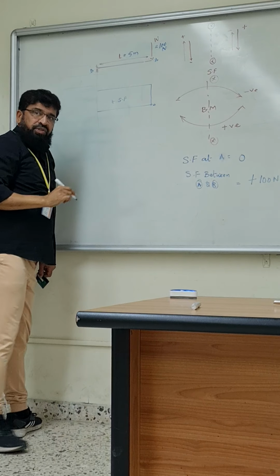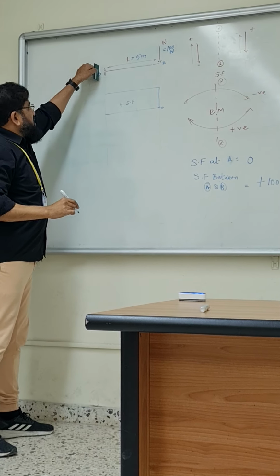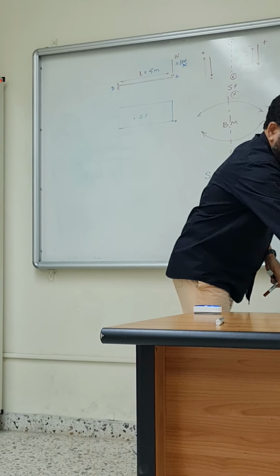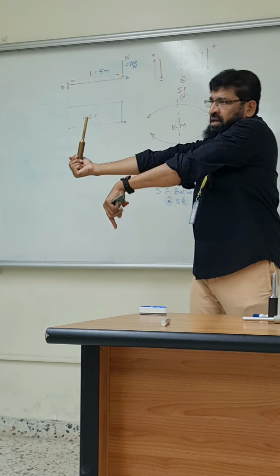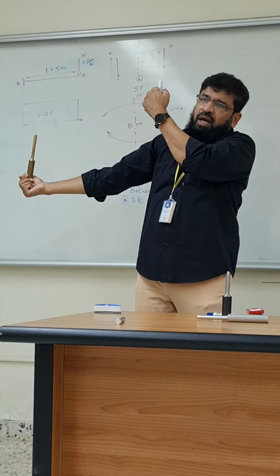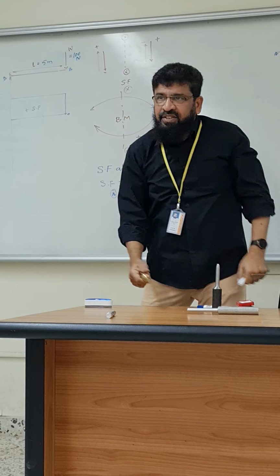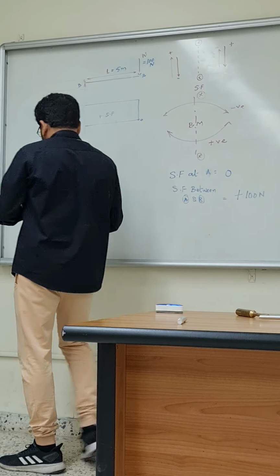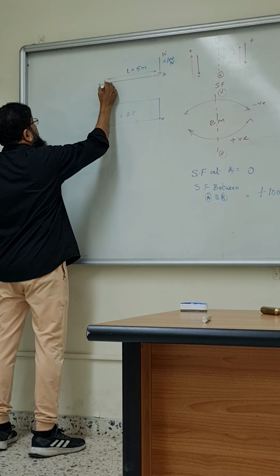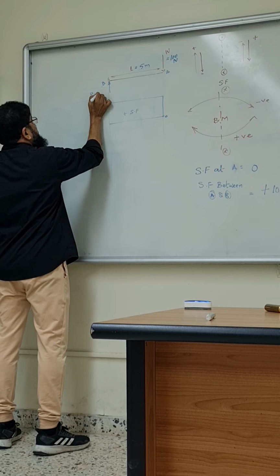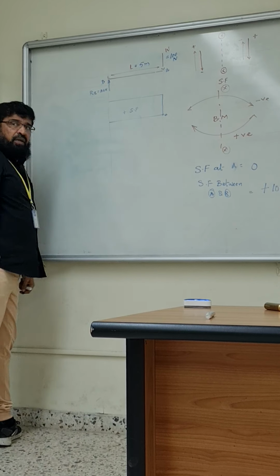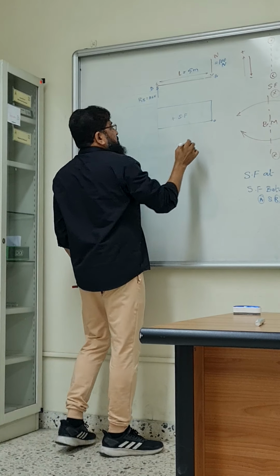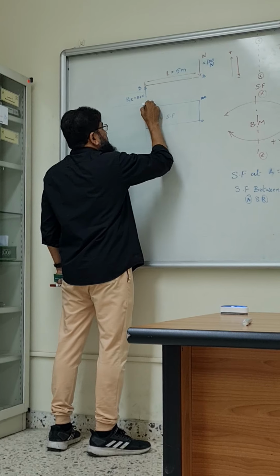This is positive. Now if I take the plane on the left side, obviously there is a reaction here. Because if I hold something in my hand like this, 100 Newton down, this has to provide 100 Newton up. Otherwise my hand will crash. So now this will be how much? The reaction at B is equal to 100 Newtons. So you have 100 here.